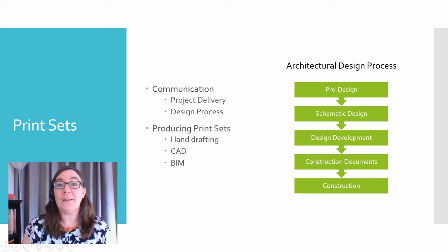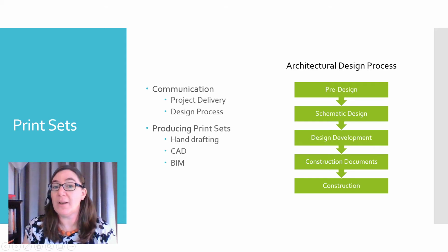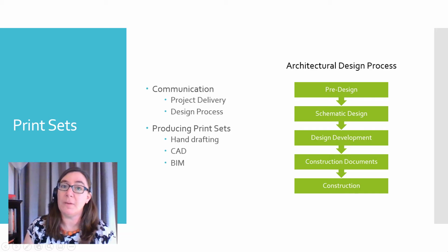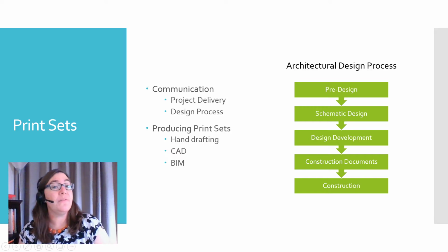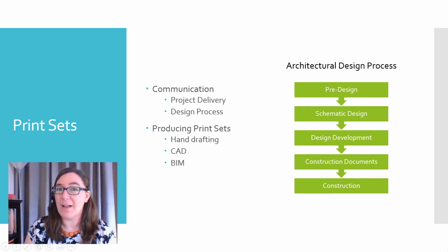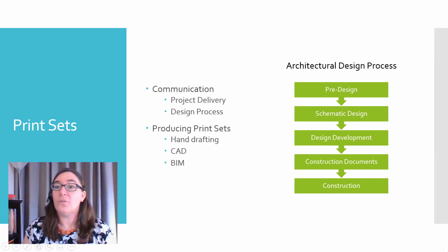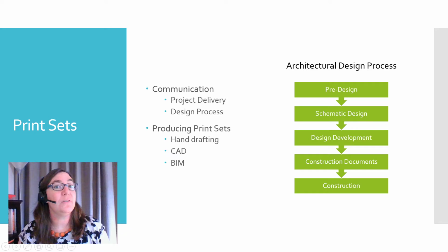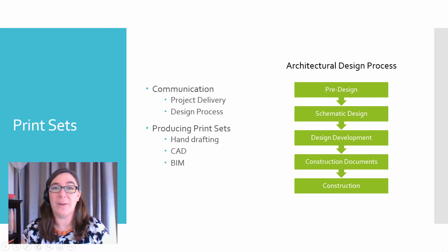What exactly are print sets? They are a communication device. Now, last week we talked about different ways to complete a project delivery systems. All right, the print sets are an important tool of communication during that project delivery process. They are developed during the architectural design process. The print sets go through a number of different iterations during pre-design, schematic design, design development, construction documents, that's when most of them are produced, and finally they are used during construction.